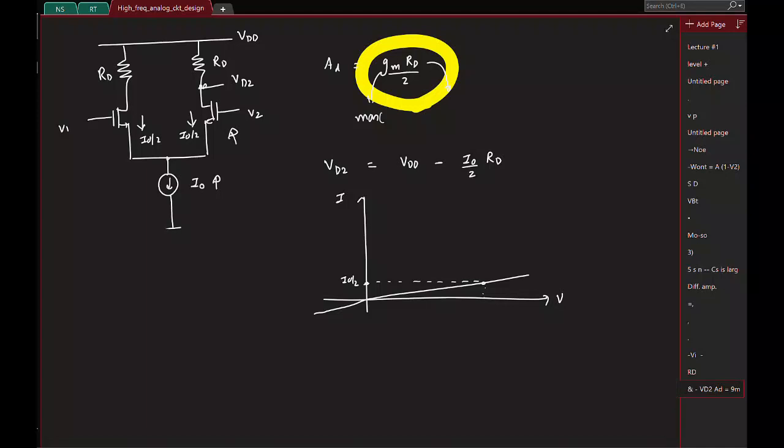So which means you need to have a large small signal resistance, right? That's all you want. So you don't need to actually have a physical resistor which acts like a resistor all the time. You can have a device that acts like a large small signal resistor like this. Okay, and then of course the characteristic must pass through the origin. So you can do this.